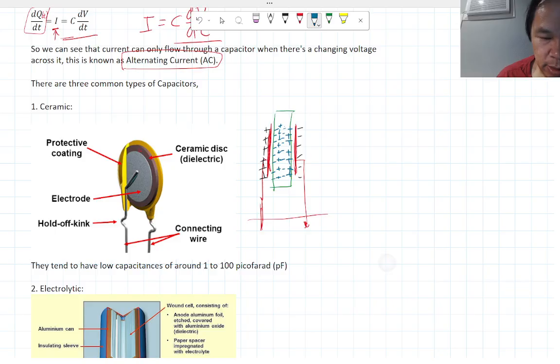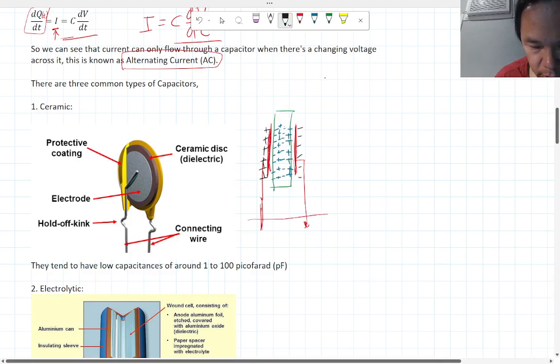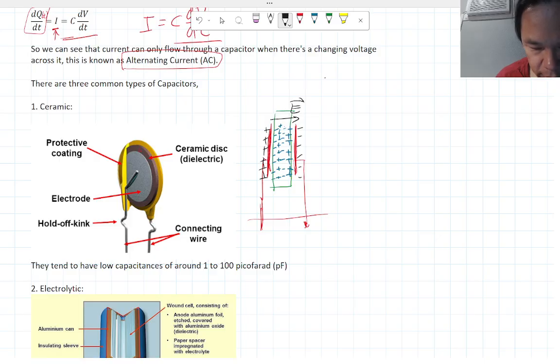Okay, what the dielectric does is that it reduces, basically, because this produces a, let's do black. Okay. The capacitor itself produces an electric field going this way from the positive to negative, but these dielectrics are producing a tiny electric field in the opposite direction, so partially offsetting this electric field.